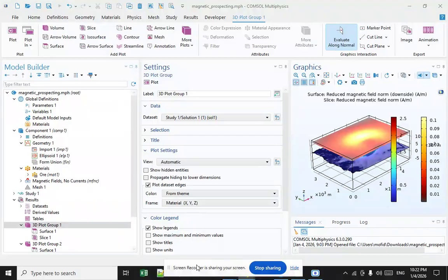Topography: the topographical map used for this application consists of a rectangular grid containing 157 by 111 points spaced one arc second apart in both horizontal directions. The curvature of the geoid is neglected in drawing this geometry from elevation data. The lower left southwest corner of the map is located at latitude 33.85 north and longitude 115.5 west.